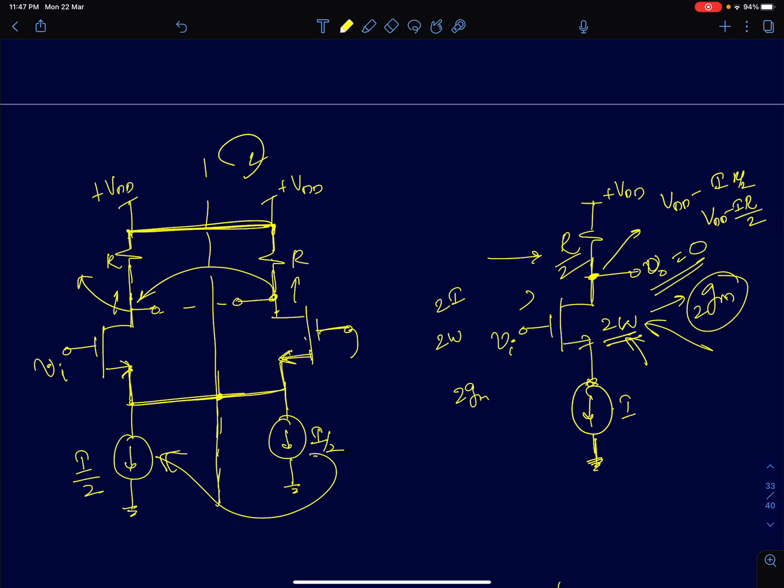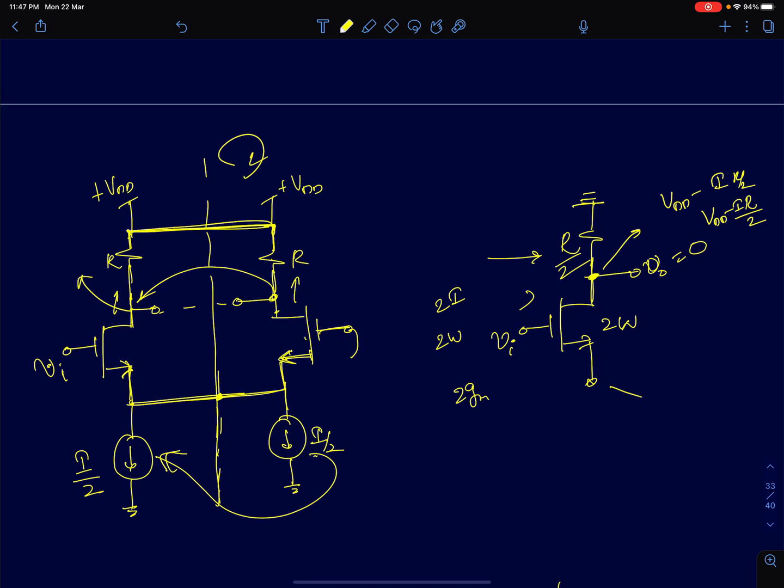So that is preserved. Then once you overlay on top of each other, all you have to do is find out the small signal AC gain: open circuit the current source and short circuit the DC voltage sources. Since the source is open, this node will also come to Vi and the output voltage will go to 0. The drain current will be 0. So I can say Acm will be 0.